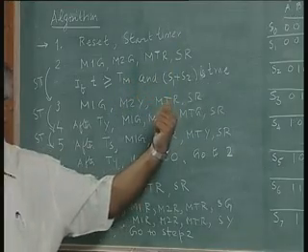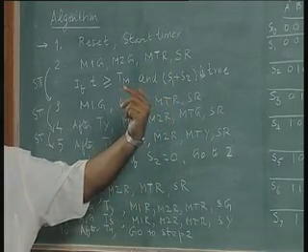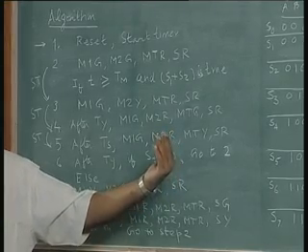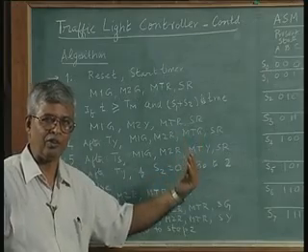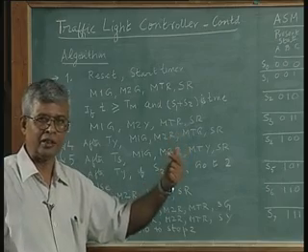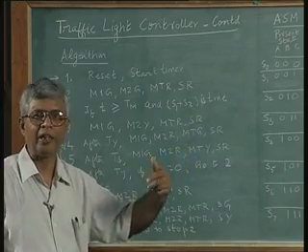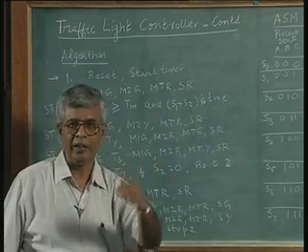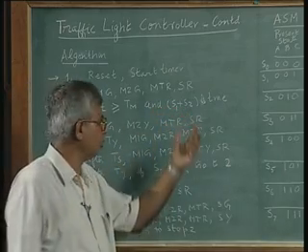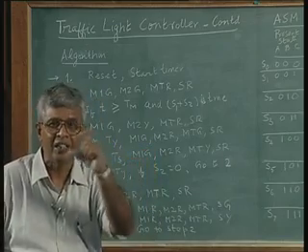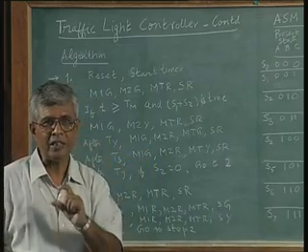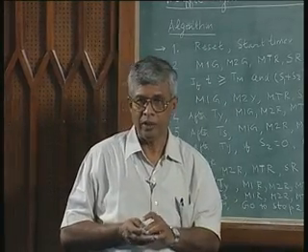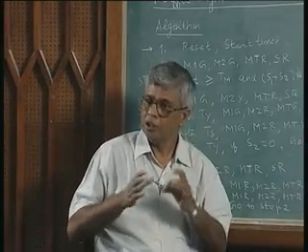I can do that. First I can check S1, like we did the RA RB case in the first example, request by system A, request by system B for the bus. If RA RB was tested and then some sort of priority, here also you can do the same thing. S1 and S2 will be tested in sequence, S1 given priority, then S2. But then each of these S1 S2 tests has to be done after every change of signal. That means the ASM becomes more complex, more states will be introduced, but if that is what you want, you can do it.